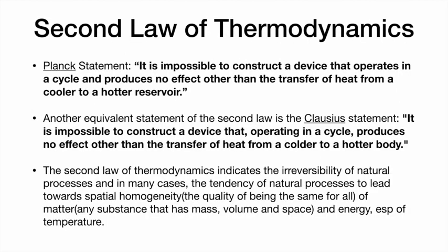Next, the second law of thermodynamics. There are two different statements for the second law. It is impossible to construct a device that operates in a cycle and produces no effect other than the transfer of heat from a cooler to a hotter reservoir. We have to deconstruct the sentence in order to understand it, for first timers. It is impossible to construct a device that operates in a cycle and also produces no effect other than the transfer of heat from a cooler to a hotter reservoir.